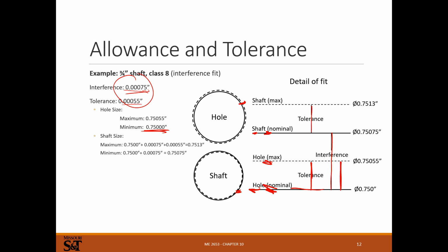It would be 1.3 thousandths of an inch would be the worst case scenario press. And then on the other side of things, it'd be here. That'd be the gap there, and that would be 2/10 of a thousandth of an inch. So it's a big range, right? So it's about 0.0013 inch on one side to 0.0002 inch would be your range for your press fits.